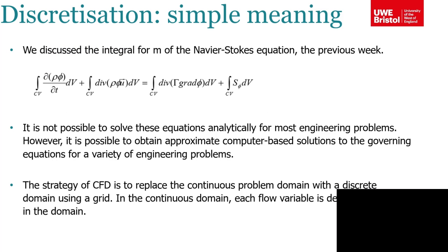So once you have written this, this is your Navier-Stokes equation and then we integrate the Navier-Stokes equation within the volume. So that is what we are doing. So that's where this sign is coming. So the control volume, in the smallest scheme of things, is the cell. Okay, so you integrate the equation within the cell, and you integrate it in the full domain when you integrate from one cell to the next, to the next, to the next. So that's what we do.